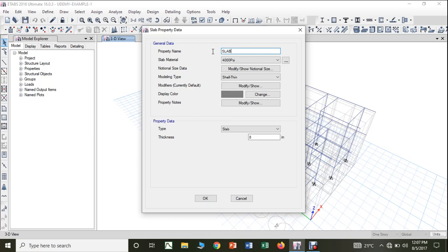Usually, in terms of engineering units, the minimum slab thickness we maintain is 100 mm, whereas the maximum slab we usually go for is 200 mm. But for any optimum residential building, we usually give a slab thickness of 120 to 150 mm.